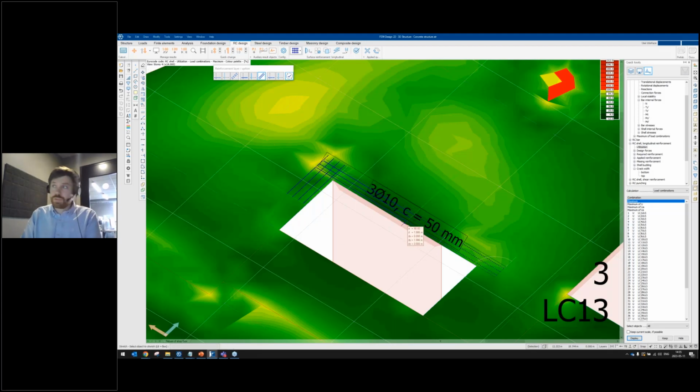So now I have changed these additional fields in the top in X and Y, and instead applied single reinforcement along the edges in this specific area where I had an overutilization. So I hope this demonstrates the possibilities, and then it's up to you how you want to do it, how symmetrical you want to do it, and the layout of the reinforcements. But this gives you much more freedom to apply reinforcement the way that you wish to do it, basically.